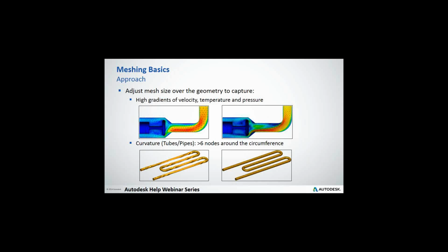Yeah, it's a whole process, actually. It begins with the coarse mesh. You focus on curvature, the geometries, the geometry components, and go further to the physical phenomena like recirculations or high gradients. This is a good input.